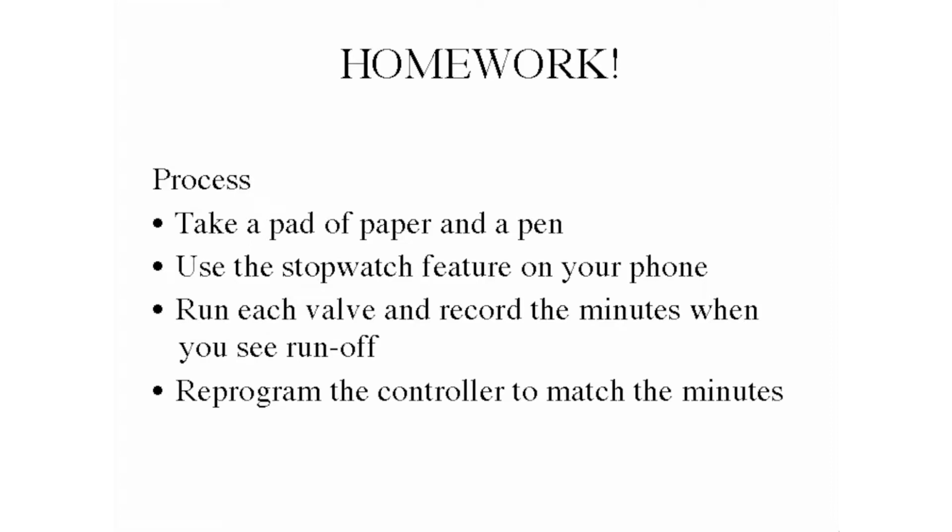And what you're going to do then is reprogram your controller for that time. So clay soil, 4 minutes, then I need to give it only 4 minutes. Now, if it was a really hot day, I might give it an additional 4 minutes. But giving it 8 minutes when I had runoff at 4 doesn't make sense. And that's why the suggestion to eliminate days is a better way to go. Make sense? Homework assignment.